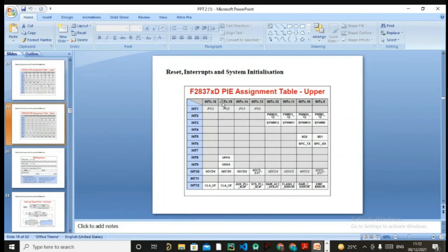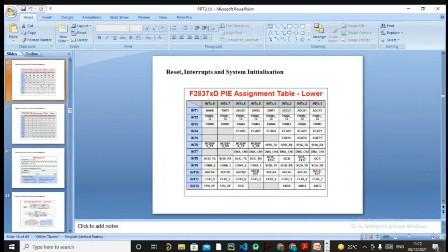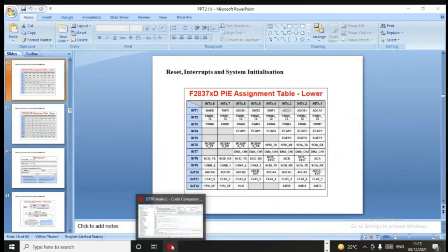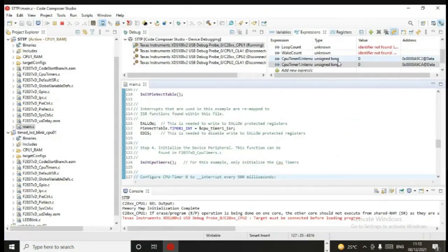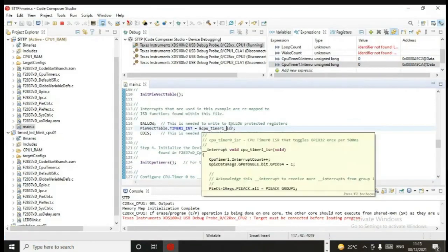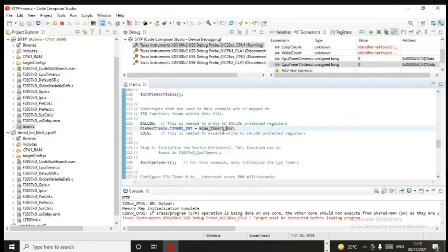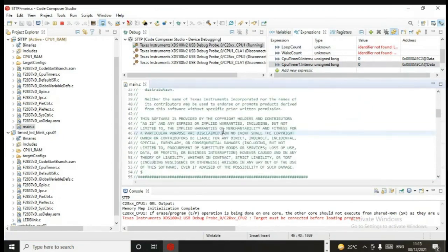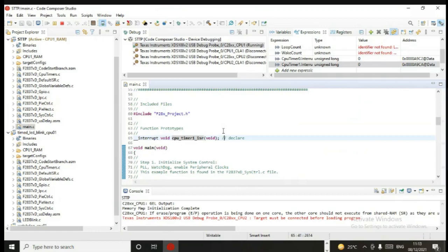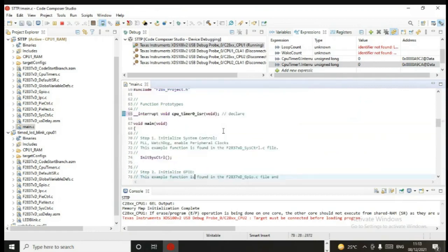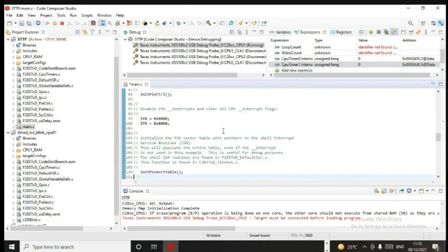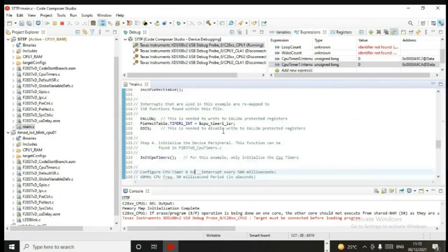So certain limitations are there whenever you are going to trigger any interrupt. You need to be aware whenever you're running any code like this. If you're not getting any output over here, as we just saw in an example, make sure that you're triggering the correct interrupt. So this is the advantage. If you are coding with the board, you will easily find out if a certain error is there. So I will just change it to timer interrupt 0 again.